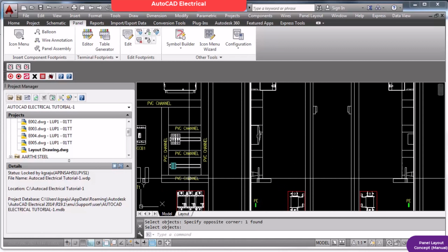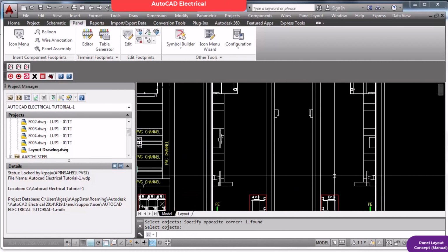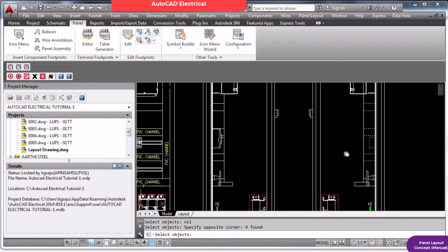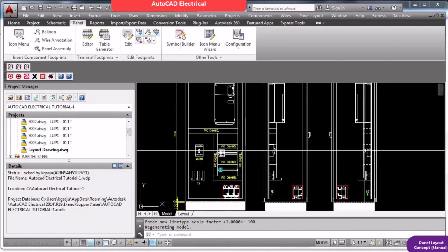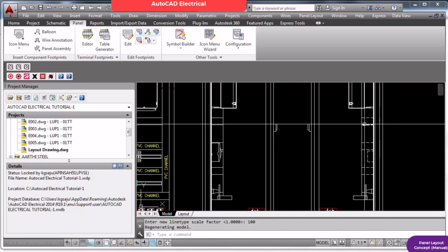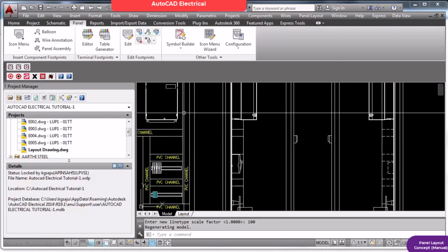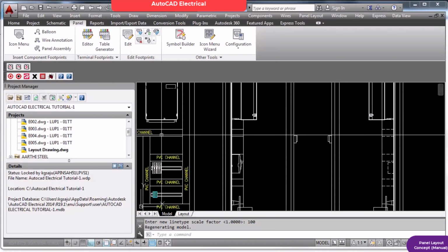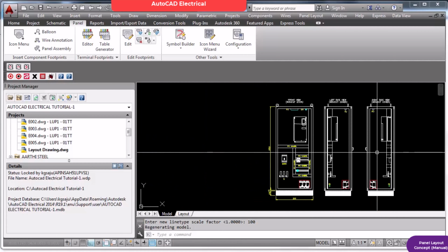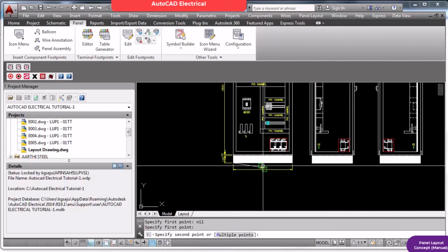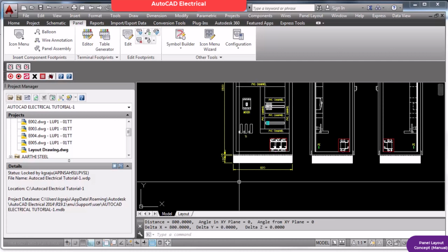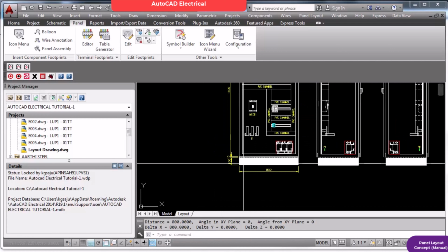This is approximately 50 mm. I know. I have drawn two lines. So this is my MCB side view. Similarly, terminals also you can make the side view. If it is not viewing from here, what you have to do is, this is standard: if you cannot view directly, you have to make those lines hidden lines, dashed lines. Okay, that means you are not viewing it directly, because here you see the duct is going through vertically, so you cannot see the horizontal channels directly. That's why I made it like this.